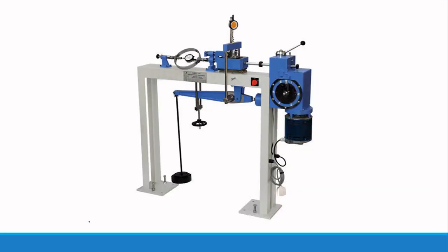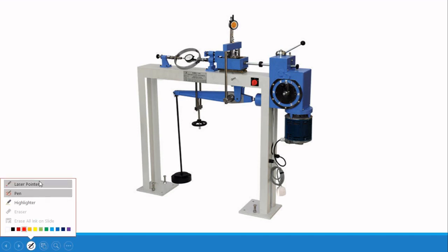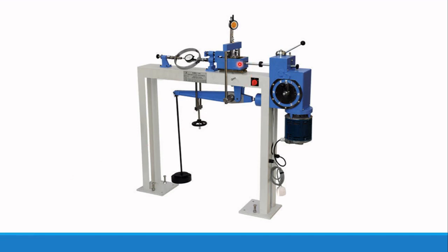Now this is the direct shear test apparatus, which is actually available in our laboratory. You can see this blue colored portion. Inside this I have the metallic box which is split into two halves. The shear force is applied through this line, and this is measured with the help of the proving ring. The normal load is applied somewhere over here and is transferred through this loading mechanism into the soil. The vertical deformation occurring in the soil is measured with the help of this dial gauge, and this is the pump through which the instrument is operated.